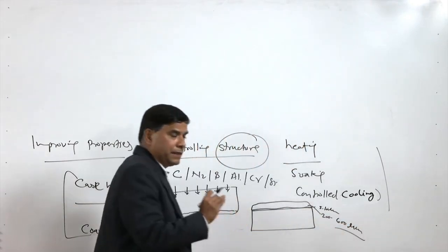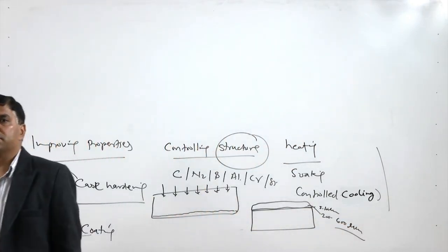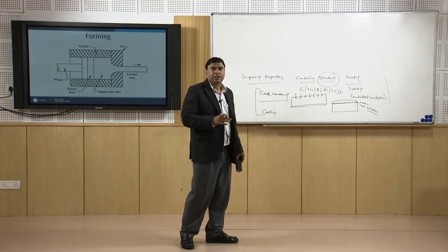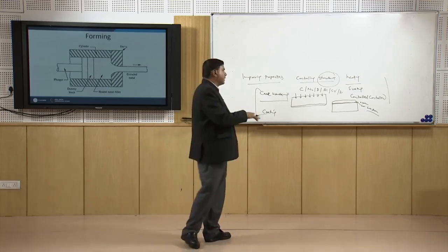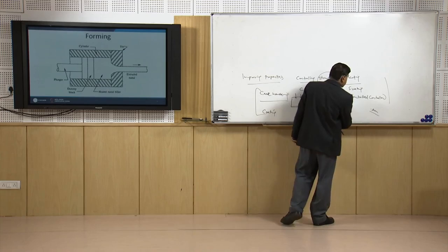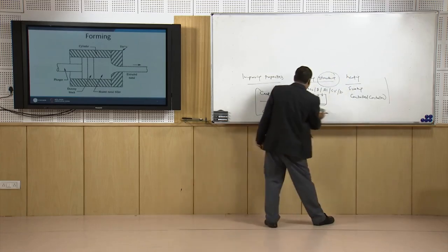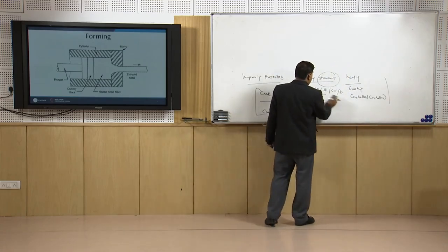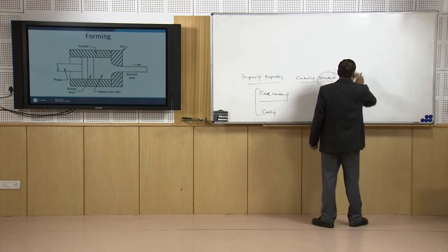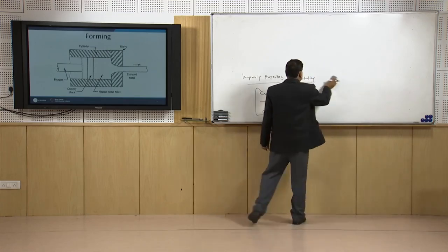Depending upon the hardness of the material, the thickness of the coating is influenced. The softer the material, the thicker the coating can be; the harder the material, the thinner the coating needs to be. As per the requirement, either hard or soft coatings need to be developed, so that the desired functionality in the product can be achieved.